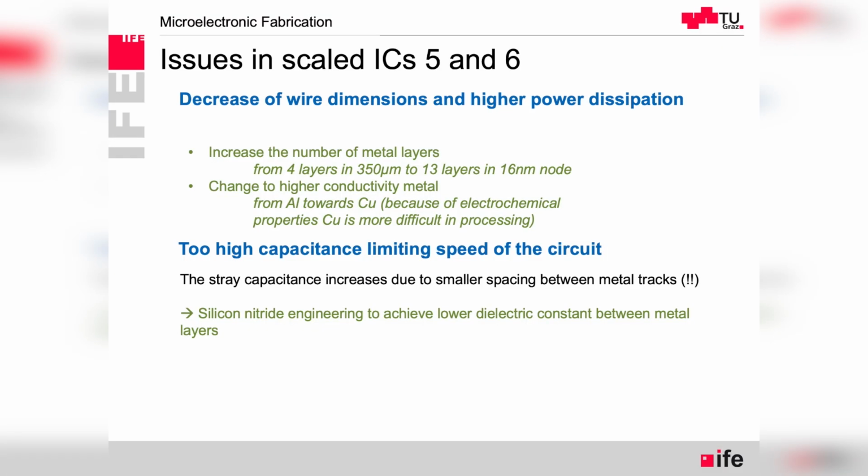The challenges 5 and 6 I group in a single slide. There wasn't a very conceptual picture I would like to add here, but I would like to explain what happens with the interconnections. So first thing, the dimensions of the transistor decrease, as I already said. So metal, we need to make thinner, especially the lower metals that are close to the transistor. So we need to separate what connects to source, what connects to drain, so those metallization needs to be narrower.